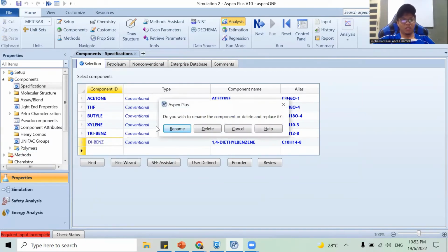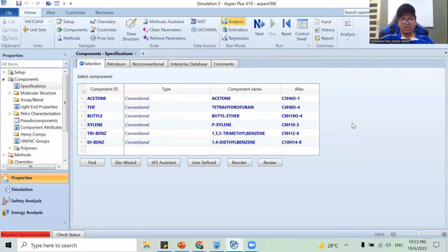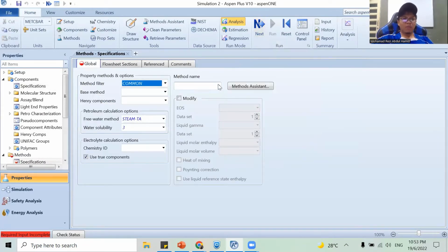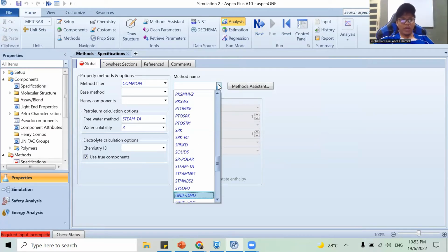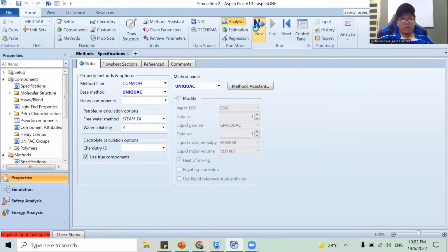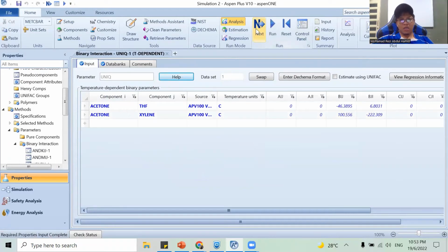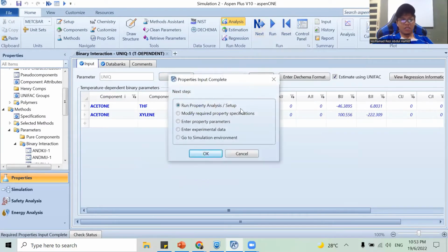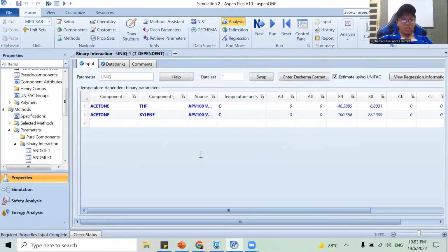BNZ should be okay. Rename. All right, should be good. And then hit next. I'm going to use UNIQUAC following the paper. UNIQUAC. Enter. Hit next. I'm just going to click this. Hit next. Okay.